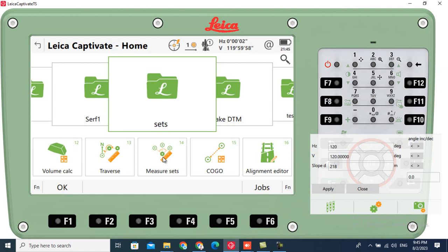But for network adjustment, I will measure all the points, including the backside, if the backside point will be used in the network adjustment. If the backside won't be used for the network, I don't need to measure it. But usually I measure the backside again with measure 6.